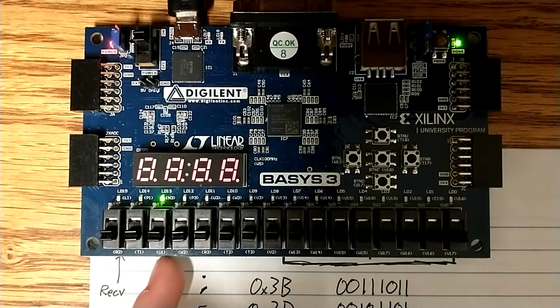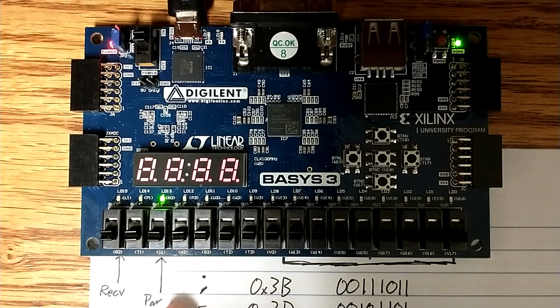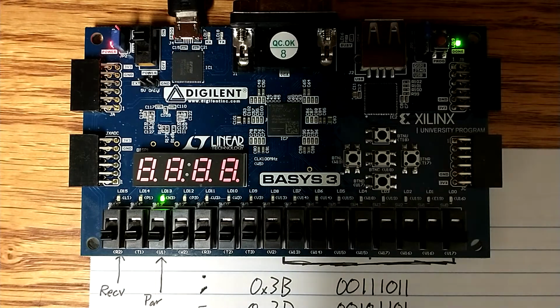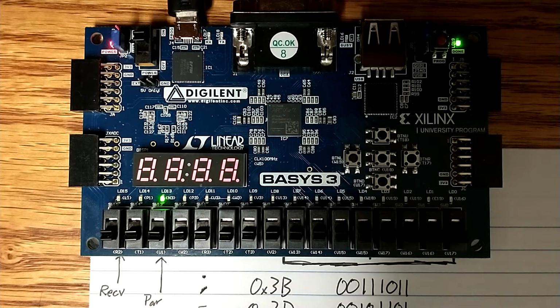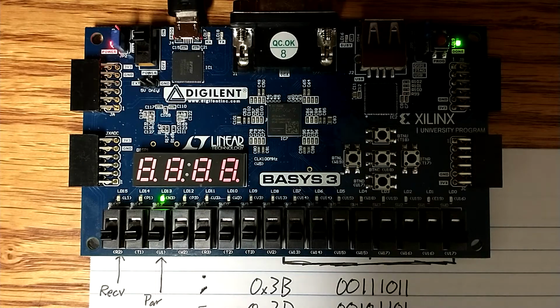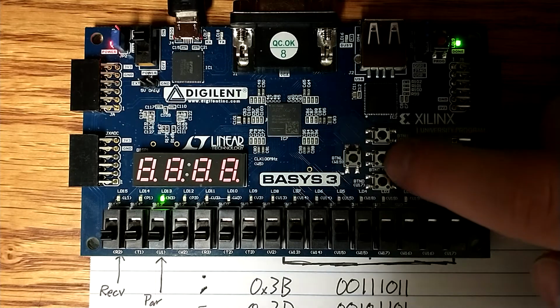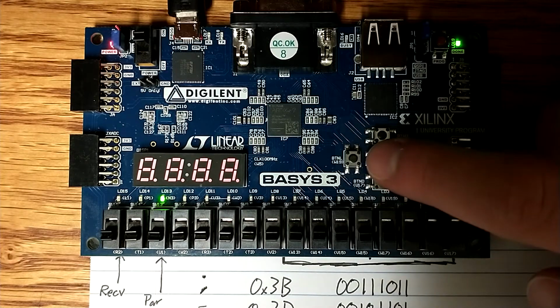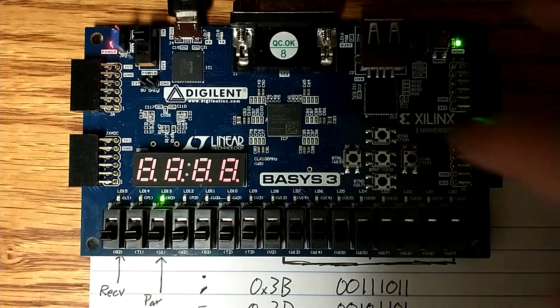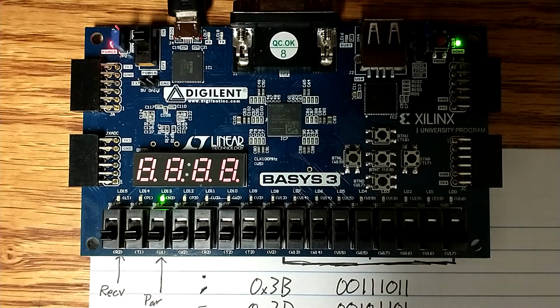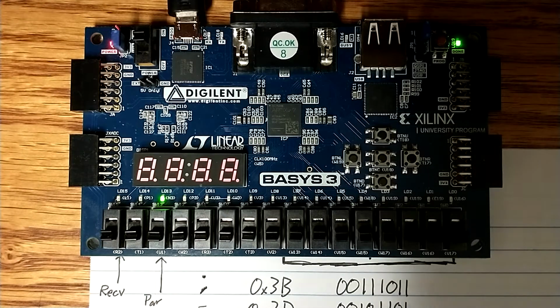And then this LED 2 spaces over, just to differentiate them a little bit better, is the parity error LED. You'll notice that it's high right now, which is just because the shift register is all zeros. So the current bit has technically an even number of ones in it, and so that gives it a parity error. And then this center button right here is what we'll use to send the received signal high, so that acknowledgement of the handshake. And then this up button will be the global reset for this circuit.